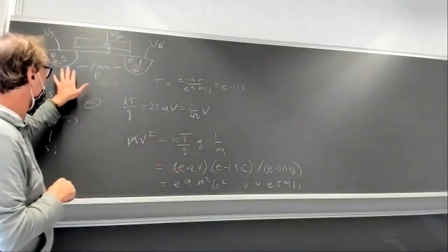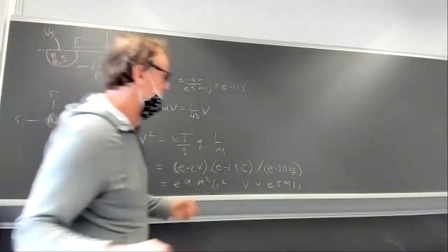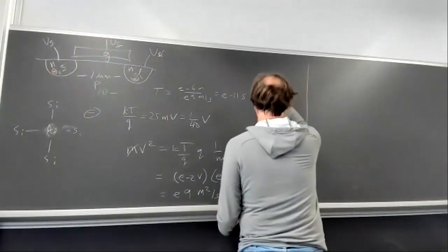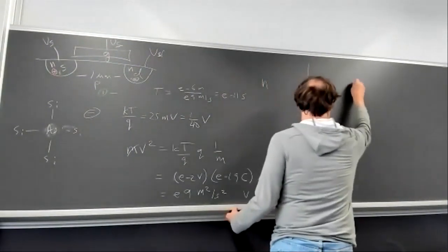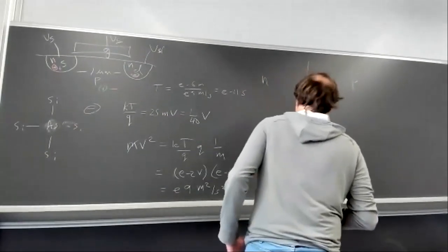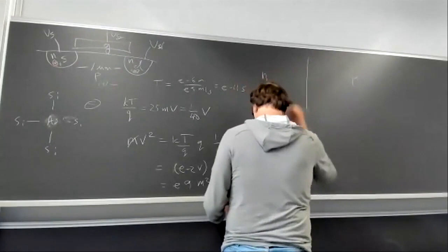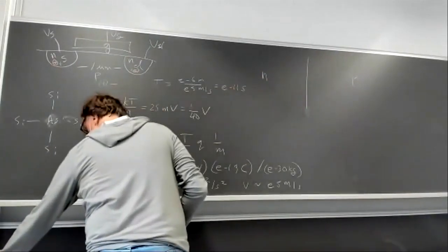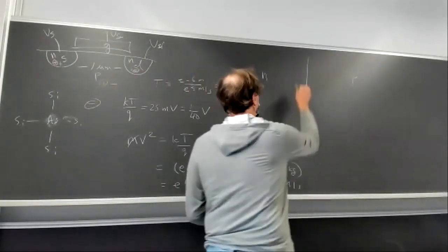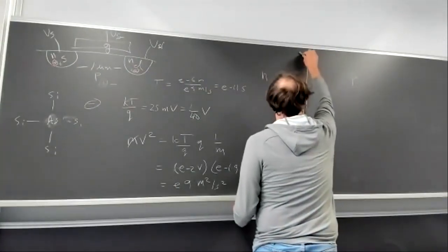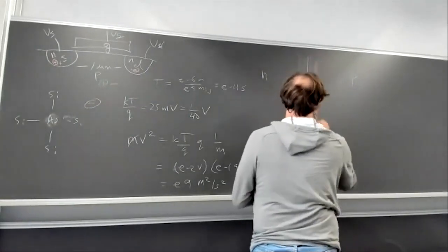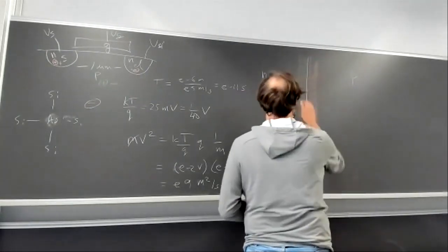So that's why you now have to draw the basic p-n junction to explain this. And you'll see it's really simple in the end. Let's say this is n doped here and p doped here. And that means, I'll just summarize it here. In the end, you're going to have a depletion region build up. I think positive here and negative here. These are fixed ions that are exposed.